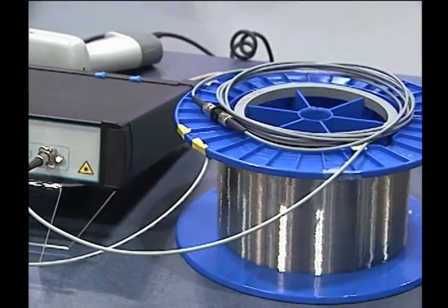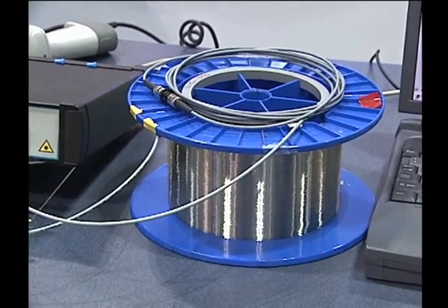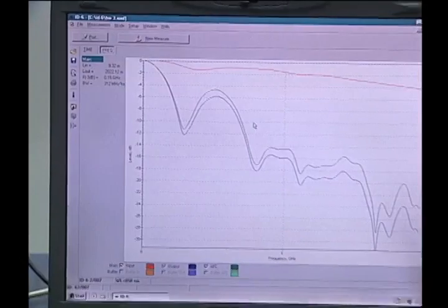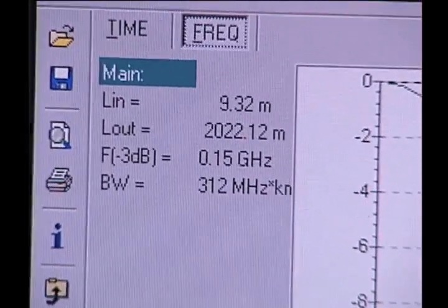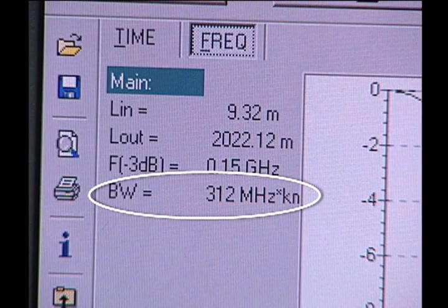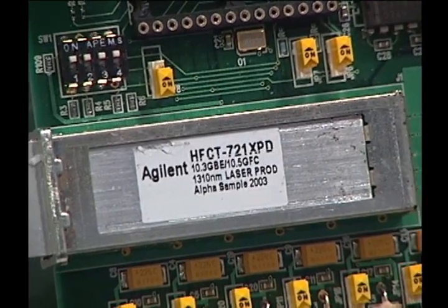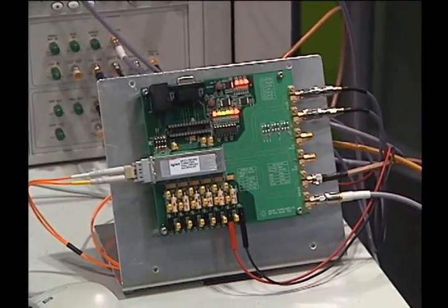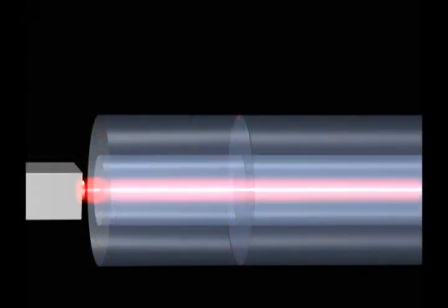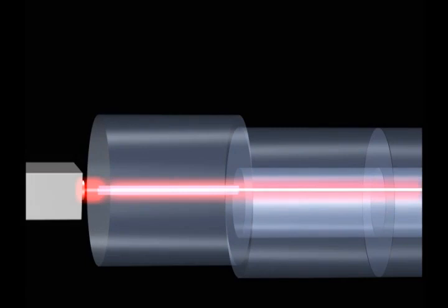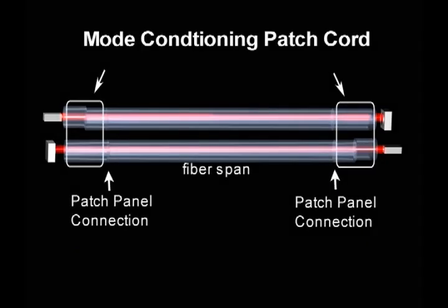Meanwhile, in the midst of multimode fiber technological progress at 850 nanometers, all standards-based fiber specifications continued to maintain 500 MHz OFL bandwidth at 1300 nanometers, ensuring performance with legacy protocols and bit rates. Even newer protocols, such as the gigabit and 10 gigabit Ethernet standards, offer an alternative functional solution using 500 MHz OFL bandwidth at 1300 nanometers. These long wavelength solutions most often use single-mode lasers, like a Fabry-Perot laser that has a very small spot size. In order to keep from focusing such a large amount of energy on the fiber center line, standards typically require a mode conditioning patch cord, which physically offsets the transmitter's launch into the intermediate and higher order modes. Such solutions are typically higher cost than the 850 nanometer technologies, but offer an upgrade option for network managers with an installed base of 62.5 or 50 micron multimode fiber.